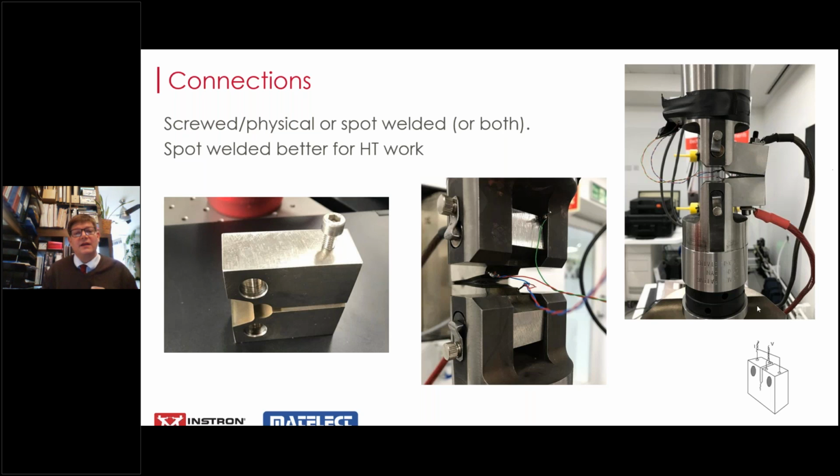So some of the famous ones are the Johnson formula and Pickard's, and there's also an ASTM note on calibration of a CT specimen. All of these have slightly different approaches on where to connect the current into the specimen and where to pick up the voltages from.